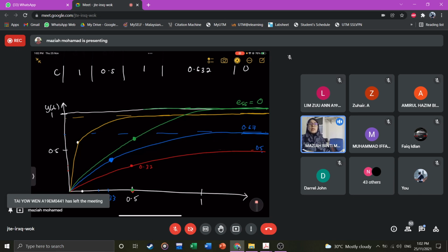So you should be able to conclude that by adding P controller, you will be able to improve the response of the system and reduce the steady state error, but cannot eliminate it. The steady state error can only be eliminated by adding I action, integral action. Then you can tune that in order to get the response that satisfies your requirement.